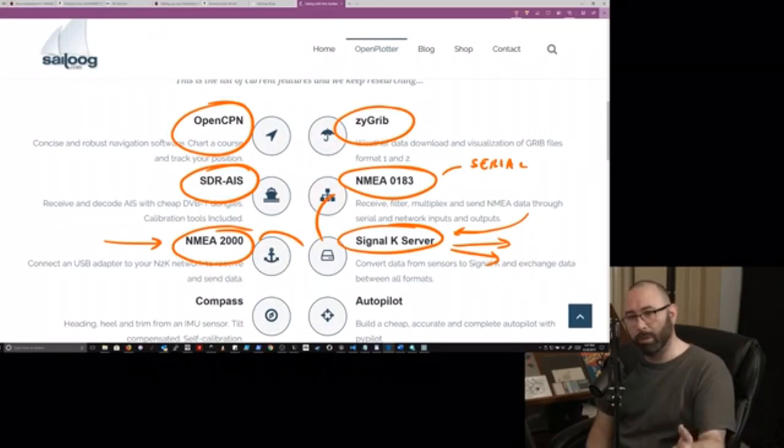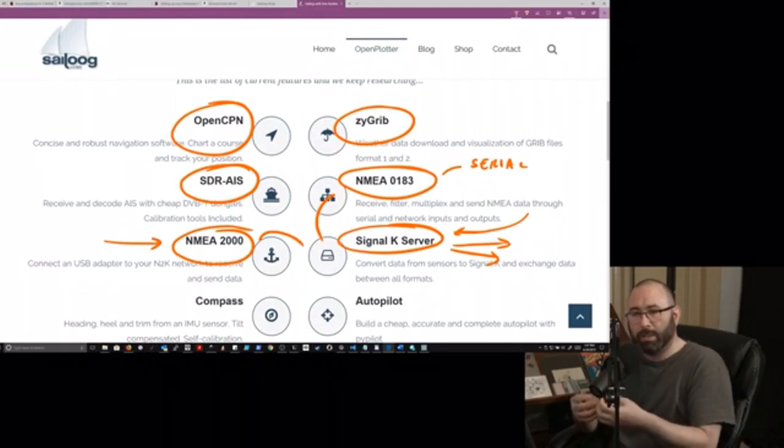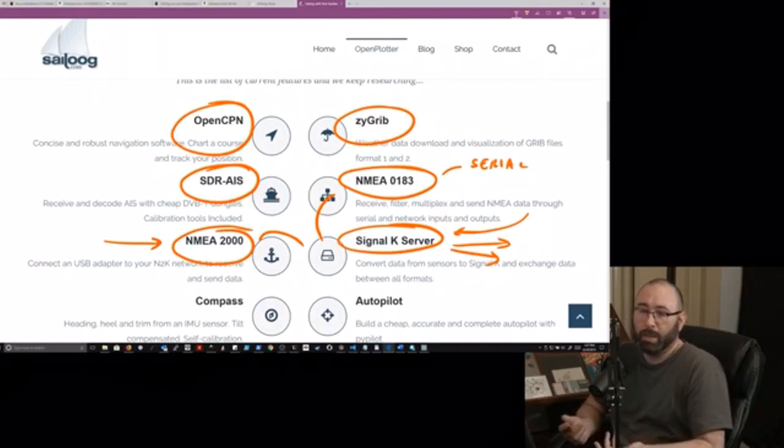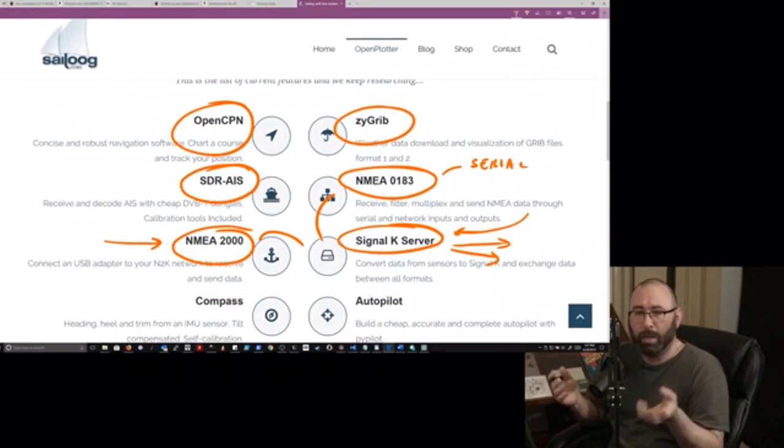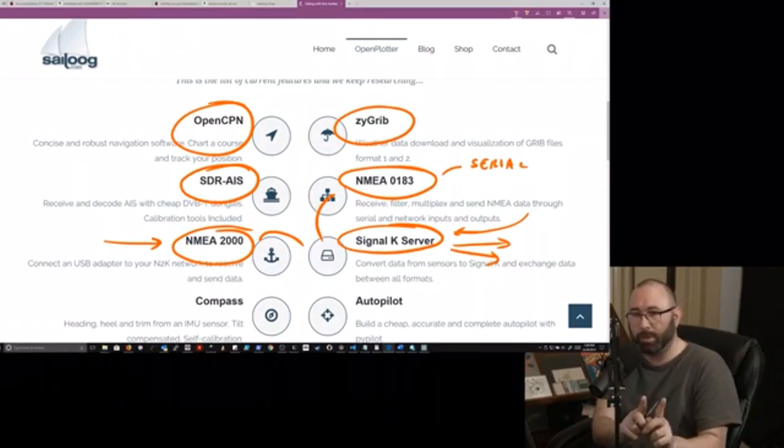This is getting a little bit more into the advanced stuff, but this allows you to extend the functionality. The example that I gave Rebecca and Patrick is if you wanted to, you could get a little microcontroller. A lot of people out there know how to do this now because microcontrollers have also gotten much easier in the last few years. You could get a little open circuit on there, and you could have two little wires, really, really simple. You could put them in the bilge, and if there was water in between those two wires, that would create a circuit, and then it could send off an alarm.